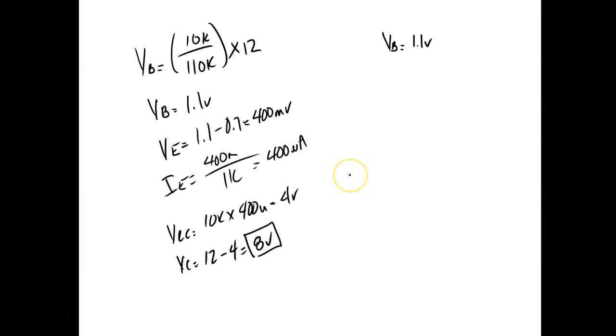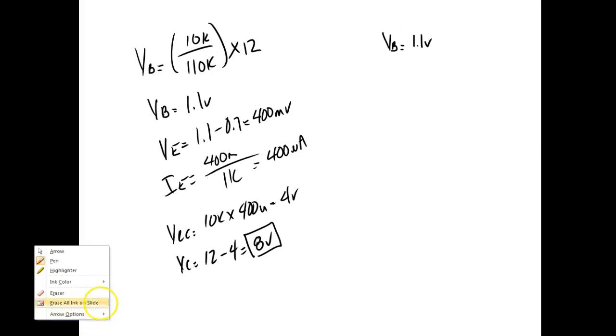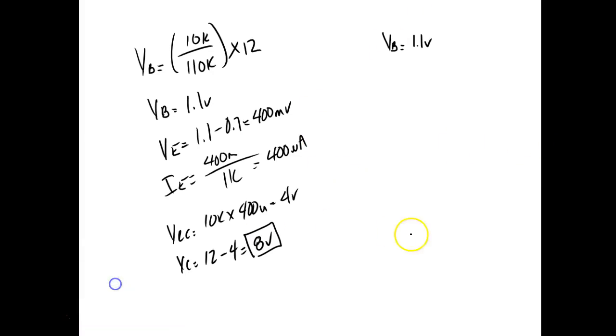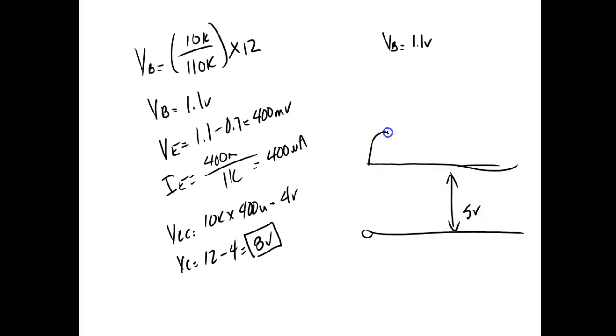Well, what's happening is I'm bringing in an AC signal. If I have 0 volts here, and up here I have, let's say, 5 volts DC, and I put an AC signal on this like this, what's my DC average going to be? My DC average is going to be right down the center, guys. So it's still going to measure 5 volts DC.